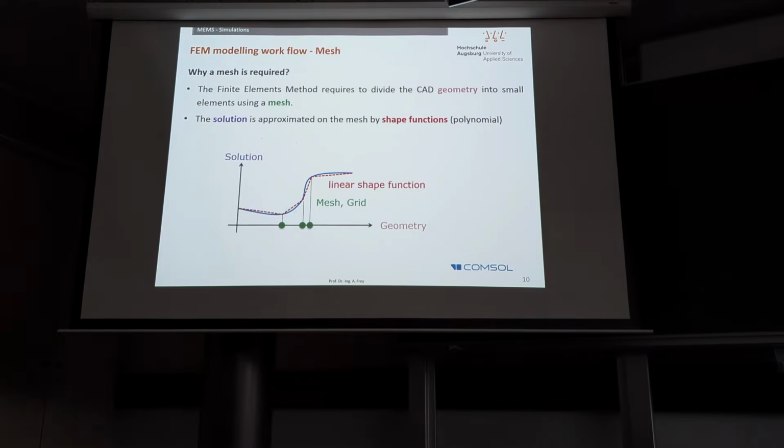In ANSYS, that would mean if you run into such a situation that the shape function has to be higher order, you would have to start rebuilding your model from scratch, because it starts with certain elements, so it's hardwired. If you start building up the model in ANSYS, you first decide for the element, and that contains also the information about the order of the shape function.